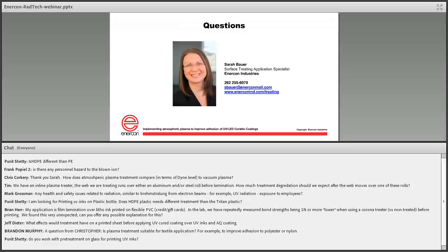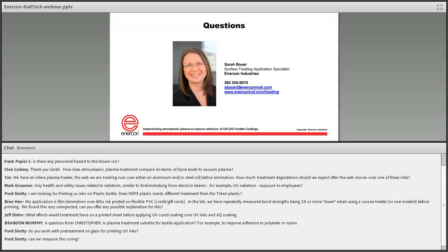There's going to be a minimum dyne level depending on your application that you need to meet, and for UV it's typically pretty high in order to get that true adhesion. The next question you have to ask is, what does good adhesion mean to me? I mentioned early on that a medical device coming apart probably has much more stringent policies on adhesion than something that's more of a decorative UV coating. So it's always good to ask yourself, how do we measure that and make sure that we are consistent throughout? But I would definitely say it's worth evaluating both types of plastics.